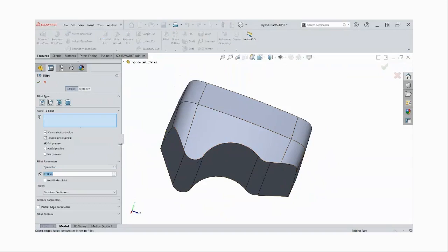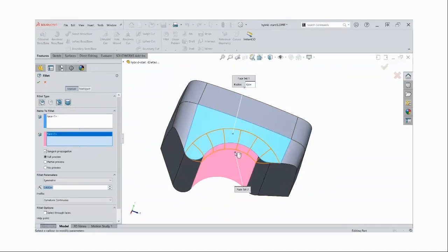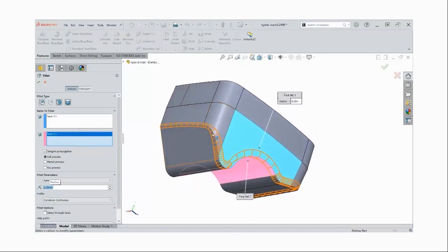And for this next one, I'm going to use not an edge fillet, which is the default, but a face fillet. So this third option is a little more work to set up. You have to select a pair of faces. And we'll lower it down to a smaller size, like 1/4 inch. And this is right now set curvature continuous, but you'll see that it tapers down.